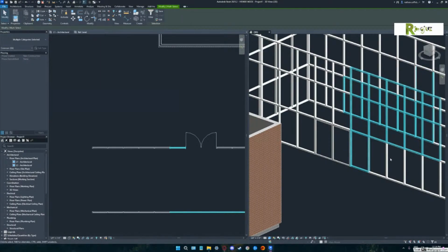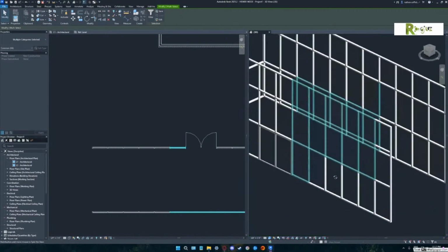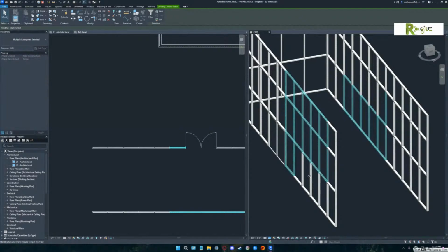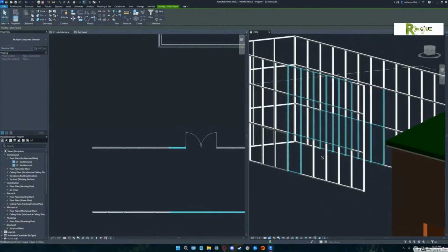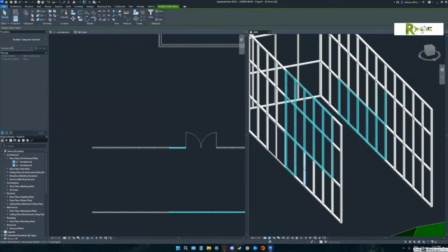You have a bunch of stuff selected. You got some curtain panels and some curtain grids from 2 different ones. I can even go one step further and tell you you've selected 66 objects. Do you have any idea how I know that you've collected 66 objects? Look right above your clock time. I see it. See that? 66? You see that little funnel? There's another funnel at the top of your screen.